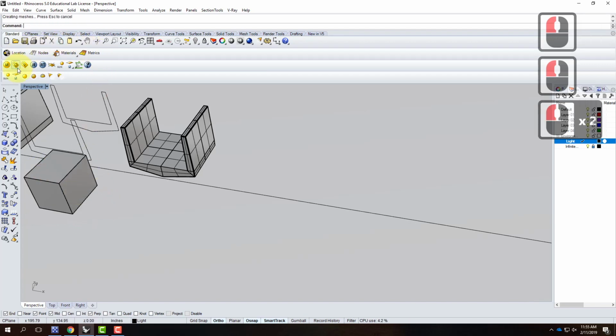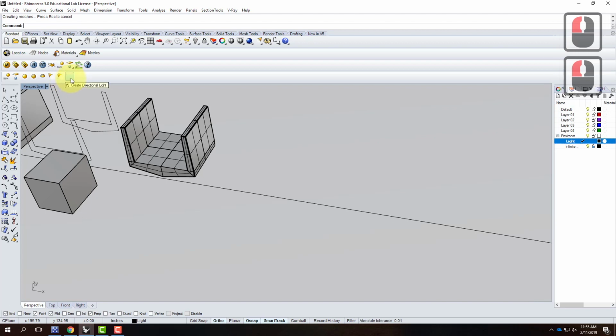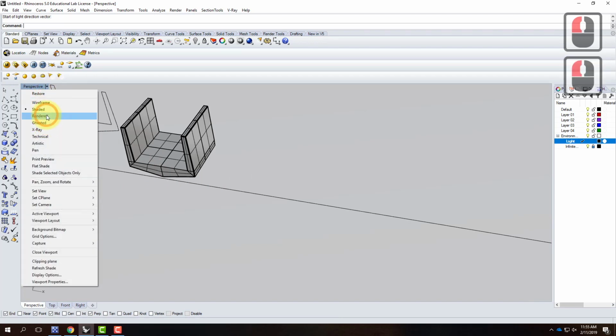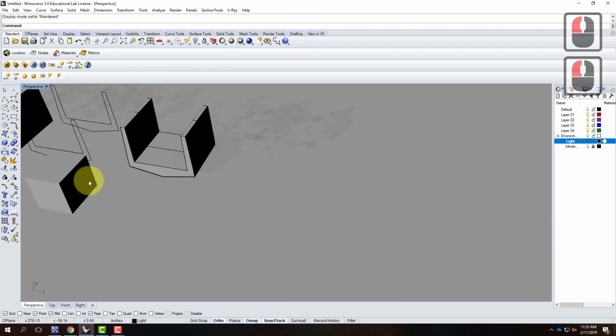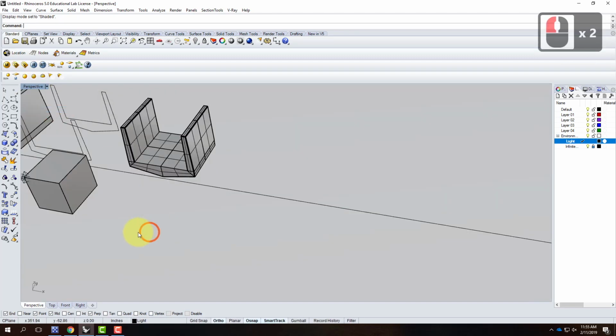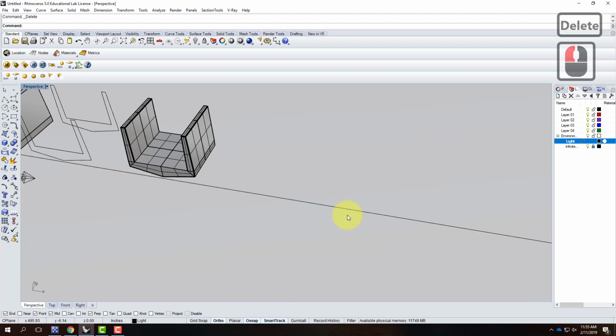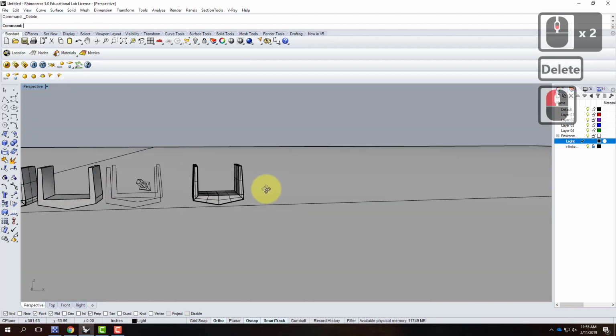There it is. I'm going to use the directional light, which is the one on the end with no icon. It's the invisible button. We'll start at the lower corner and snap up to the upper corner. Some of you, when you switched into your rendered preview mode, had everything on the ground black. If that happened, chances are your light is perfectly parallel with the ground as opposed to being up on an angle. So make sure you create the box and get it up on an angle. So I have my light up on the angle.